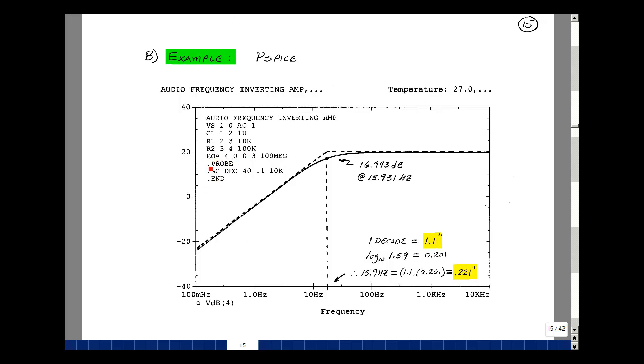And our voltage controlled voltage source, the plus terminal was at the output node 4. The ground was the negative terminal. And then we're sensing from the plus node to the minus node. The plus node is grounded and the minus node is node 3. And we're giving it a very large gain of 100 million. And the dark line here is my response.